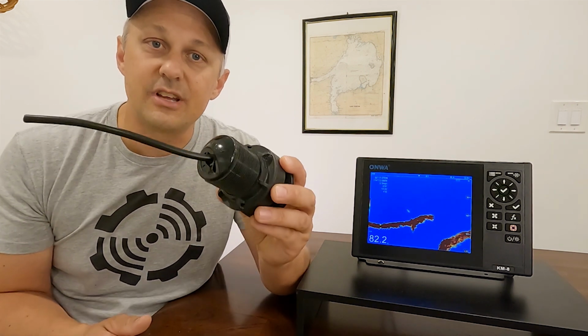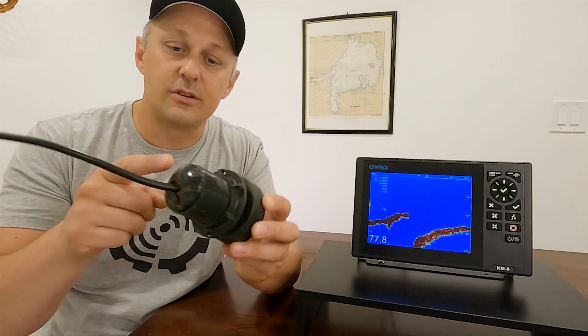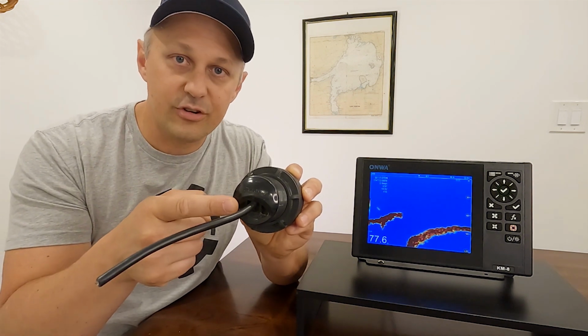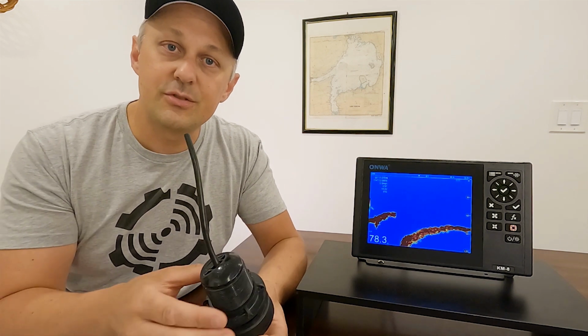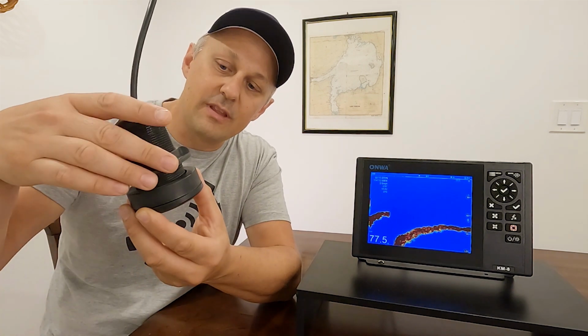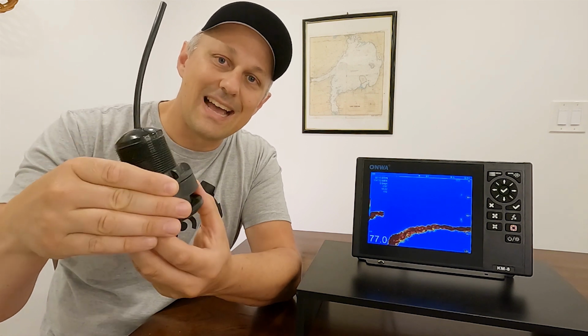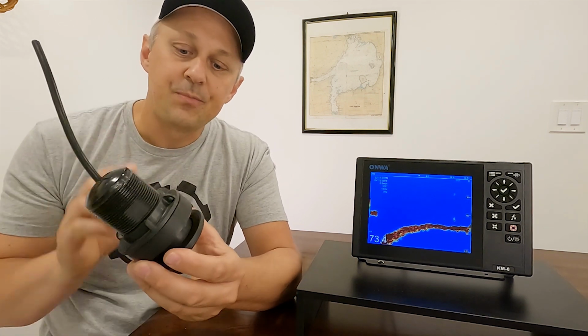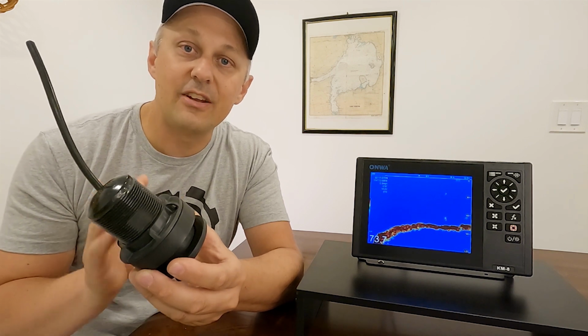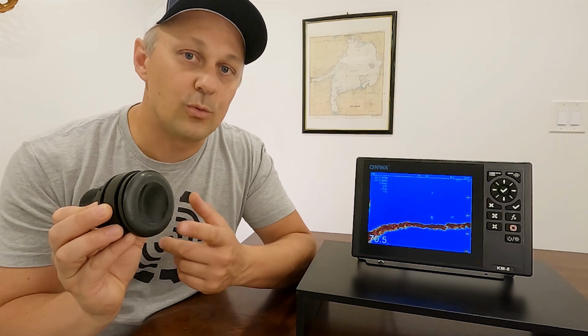Now, if you have a boat that has props that are in front of the transom, like inboards for example, you can't mount a transducer behind them because you'll have too much turbulence and air bubbles, and transducers aren't going to read through air, they're just going to read through the water. So what we would do in that case is use a through-hull transducer. With a through-hull transducer, we cut a hole in the bottom of the boat, the diameter of the transducer, which is usually 2 inches. The transducer and cable are then fed up through. This nut would then be cinched down to compress it tight up against the hull, and marine sealant would be used to create a waterproof seal. This will allow you to get the transducer in front of those props to maintain a clean flow of water over the face of the transducer while your boat's underway.